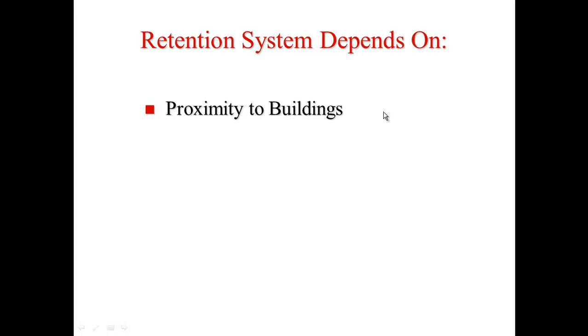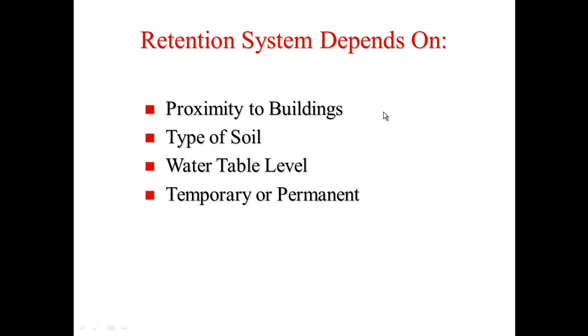Retention systems depend on proximity to other buildings, types of soil you have, water table level, and whether it's a temporary or permanent type of retention system. Maybe it's going to stay in and actually become part of your foundation wall, like the slurry wall. Contractor preference matters too.